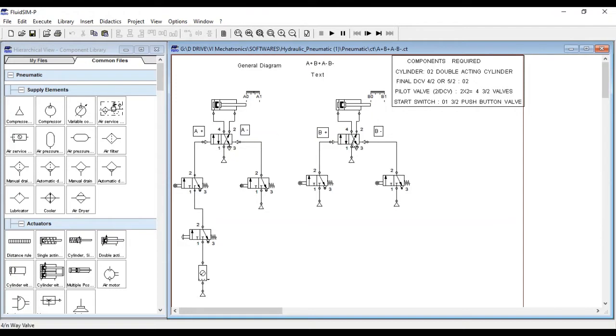Now these direction control valves are pneumatically piloted. That means supply has to be given through a certain switch so that it can be turned on. So if I want A plus, I want to make this switch turn on. This is nothing but a roller switch. That means when I want A plus, I want to actuate this. This should actuate and then I will get my A plus. Similarly, this valve will be actuated, then I will get B plus, and then this one I will get A minus, and then this will provide me B minus.